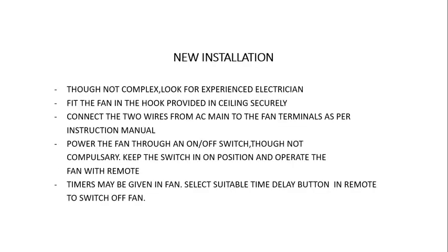When you are doing a new installation, follow these instructions. That is, it is better to look for an experienced electrician. Fit the fan in the hook provided in the ceiling securely. Connect two wires from AC mains to the fan terminals as per instruction manual. Power the fan through an on-off switch. Though it is not required, you can power the fan through an on-off switch. Keep the switch in the on position and operate the fan with remote. Timers may be operated as per your requirement.